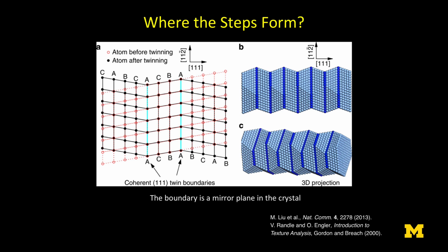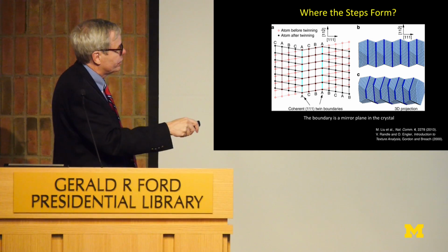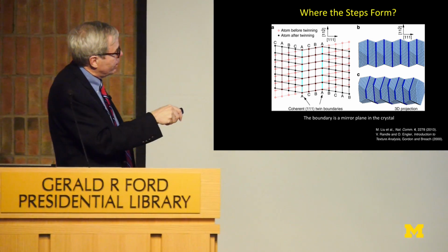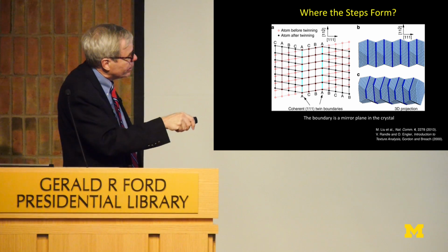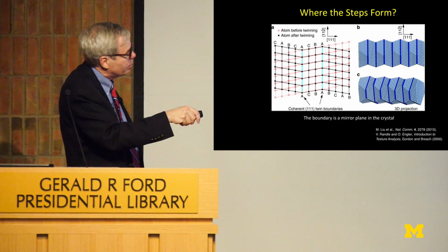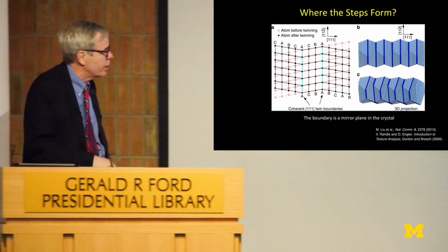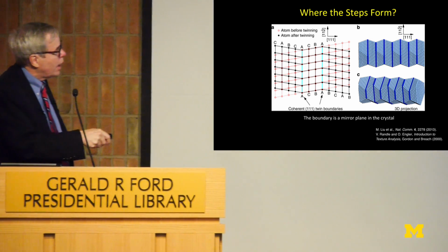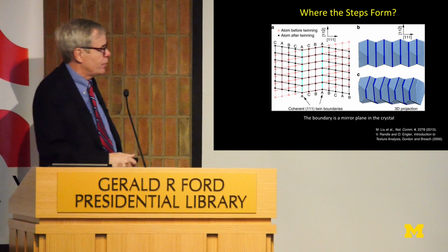And so if you take a crystal lattice here and create a twin defect along here, and it really is a twin in the truest sense of the word, that if you put a mirror along here, this side of the crystal looks exactly like this. So it is a mirror twin. And in 3 dimensions, it looks something like this, where the atoms go up and down and up and down. The atomic planes go up and down with the twin defects here. It turns out these twins are very important in the growth of silicon, as we'll show you in a second.